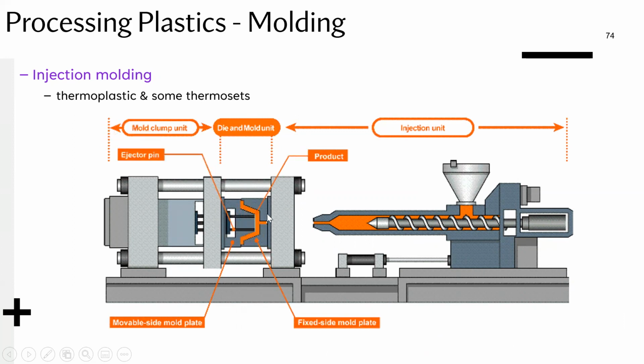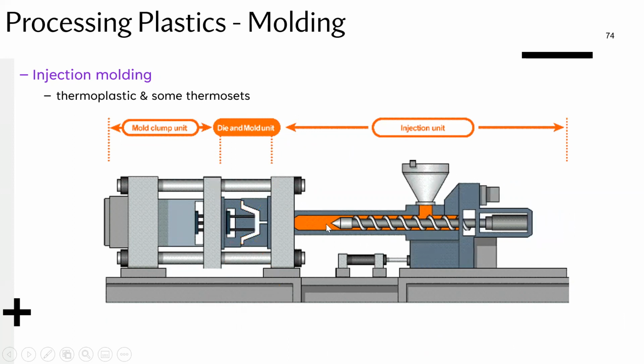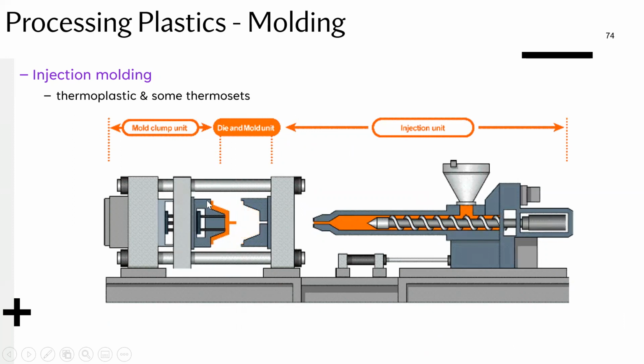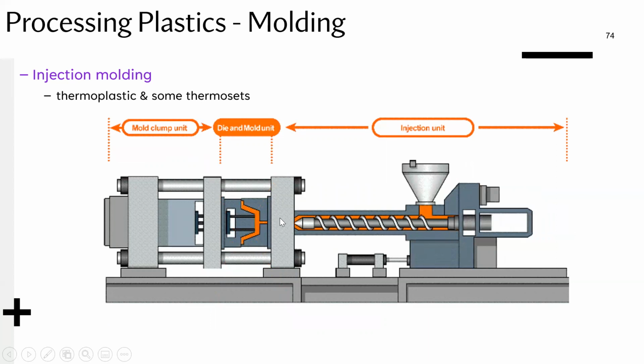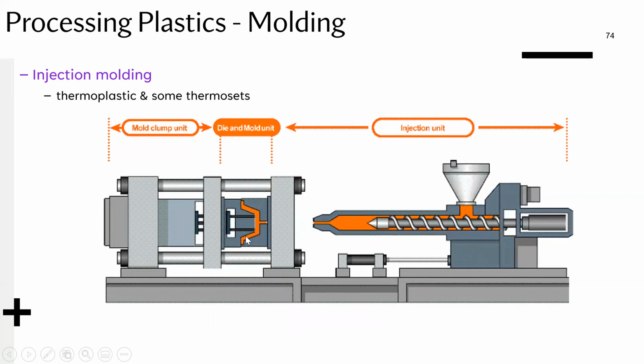So these are the ejector pins. You need them to release the object. What you see here is the injection phase. Then we've got the object, you release it, and you move on to the next one. The difference really is that here you're taking it to the liquid state, and then you've got a syringe-like injection system, feeding it into the cavity, and then you're releasing it.